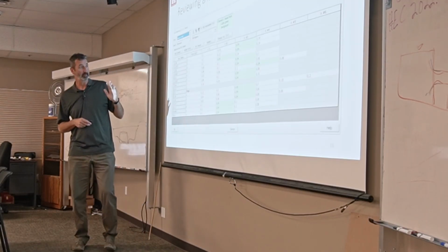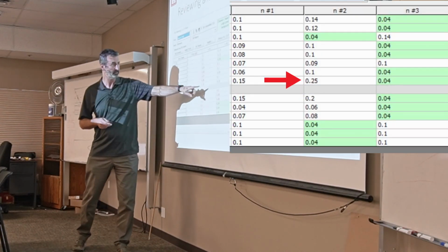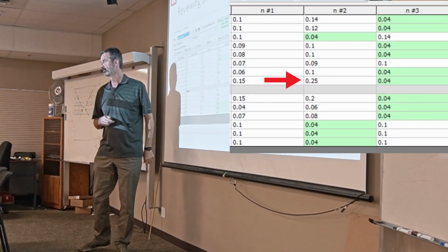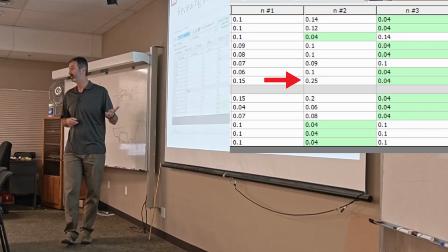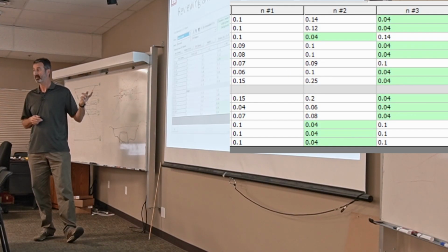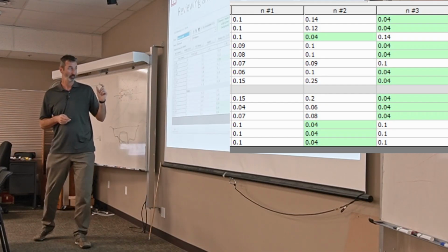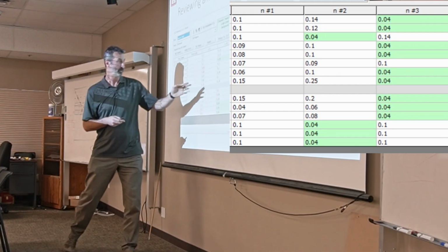But that's all good for input. But for output, it's also good to go and just have a look to see what are the n values. So n value 0.25, that's really high. Oh, so if someone was trying to achieve something there, what were they trying to achieve? They wanted there to be no flow for part of a cross section, right? No, they wanted to take the conveyance and say, well, way less conveyance is happening for whatever station this is.